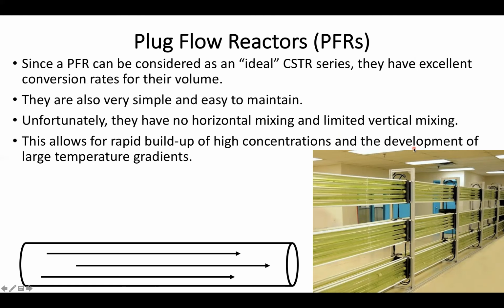But again, one of the similar problems is that if we have unfortunate pockets of high concentration, this can also mean we generate high pockets of temperature. So some of these large temperature gradients can be rather unfortunate for the system, especially if you're building it with off-the-shelf plastics, where we can have some degradation. So one of the easiest ways to address these issues is by trying to build in mixing reservoirs somewhere in the middle, as well as introducing things like baffles.